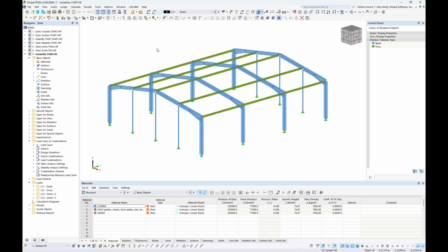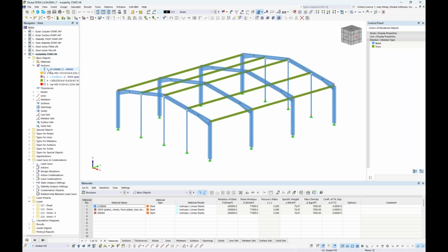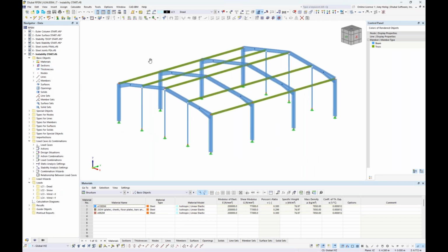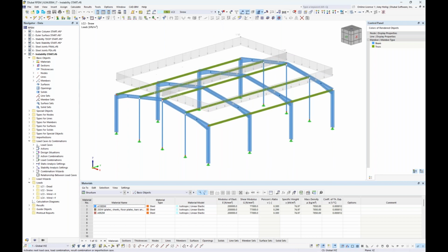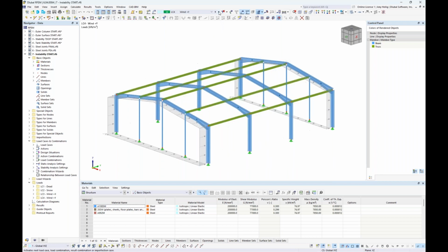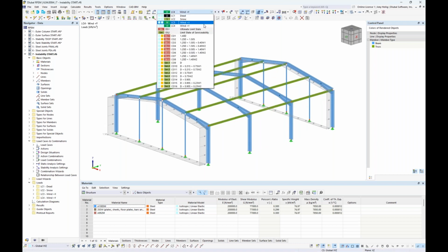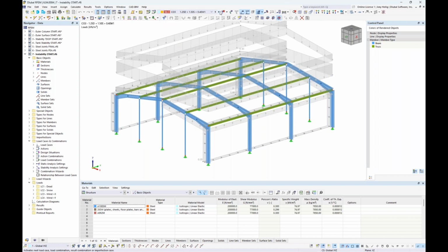So we have here just a general steel structure, again, modeled with all beam elements, and these come directly from the CSA standard this time with W250 by 80 steel shapes here, some HSS members, and so on. I also have some various applied loads. So we'll see the dead load applied here is an area load. We have snow load, and then we also have a couple wind loads in the global X direction and the global Y direction. And all of these are combined into load combinations here according to the NBC standard.